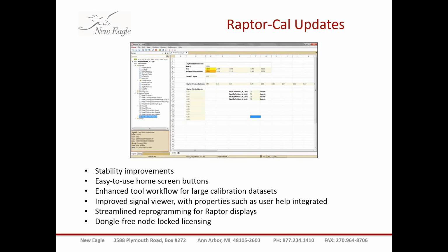Thanks, Chris. So the thing he was mentioning about the speed of the logging, that's due to the DAQ capability within XCP, and it's actually at whatever your foreground rate is. So if you've got a 1 millisecond foreground, you can log your data at 1 millisecond.